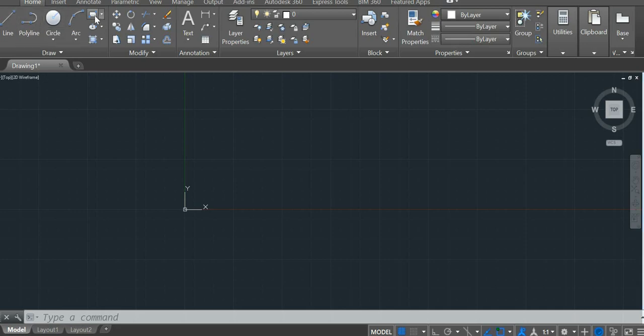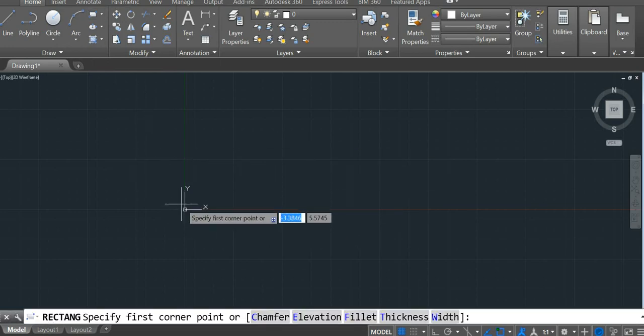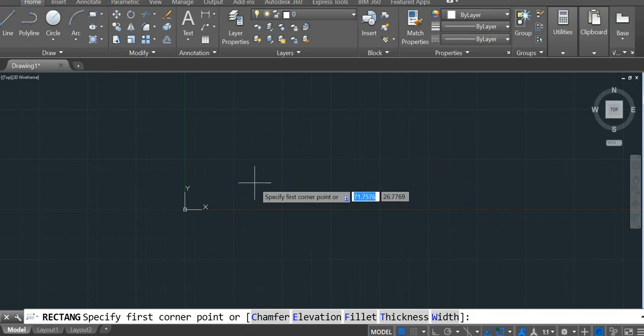Okay, so this is for the first tutorial, how to get your hull shape. So we're going to draw the widest part of our canoe first. The minimum width that it needs to be is 520 at the front and 420 at the back. So the middle should be maybe a little bit bigger than that if you want it to fit the paddlers. And the maximum width you can do anywhere at any point in your canoe is 900 millimeters.